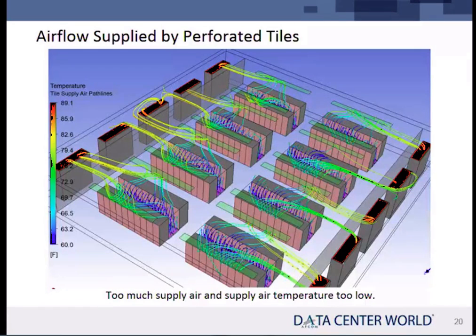If the air balance was perfect, if all I was delivering is what the system needed, there would be none of these returns going back. But you see they are. There's a few going back. I'm over-delivering air. I'm getting bypass airflow, and it's going back and it's cooling off my heat exchanger. And that's reducing my efficiency. So a perfect picture would be none of these returns going back, none of these yellow ones.